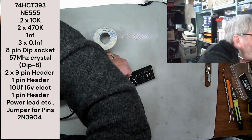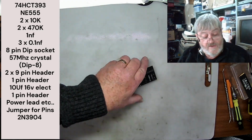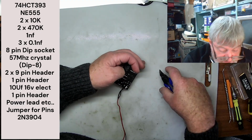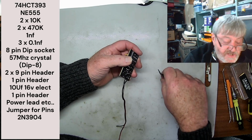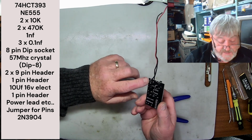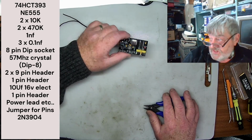Yep, it's all good. And that's just about everything done. So all I need to do to use this in the circuit for the 728 is power it up and sort out a way of injecting the clock signal into the computer. And if I need to, I can pull a ground off of this as well, or off the top here. I could put a ground pin on here. And that's it done, guys. So that's how simple it is.